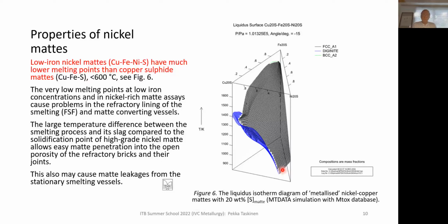construction details, through the corners of the settler or some other part of the furnace. And it is dangerous in such a sense that if you look at the temperature where these mattes are fluid, where they are molten, they are below that limit where your eye sees that it's hot. Solid and liquid parts start glowing when their temperatures are close to 800, and this may be close to 600.